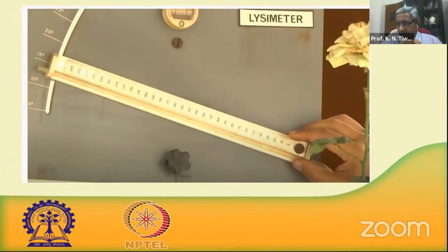You write, what is the mathematical relation between lysimeter and sensitivity? Well, lysimeter and sensitivity are two different things. A lysimeter is a device used to find out the evapotranspiration requirement of the crop. Now, how sensitive is the lysimetric device? That is the question: how sensitive is it to any smaller change in the gain in soil moisture content, or a smaller amount of water withdrawn by evapotranspiration, whether it is shown by the meter or some device through certain measurements.